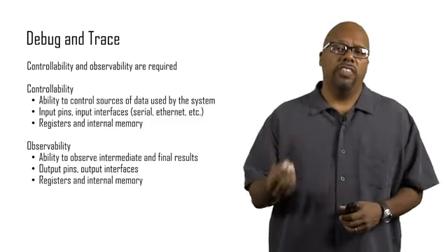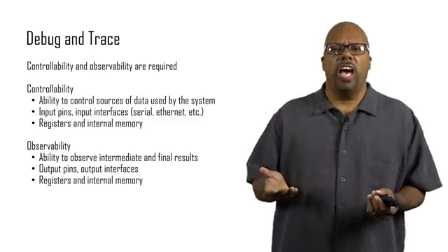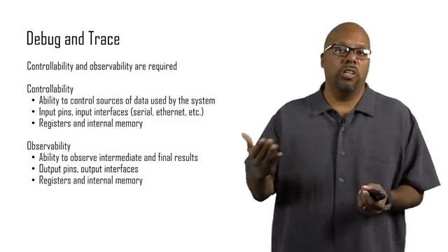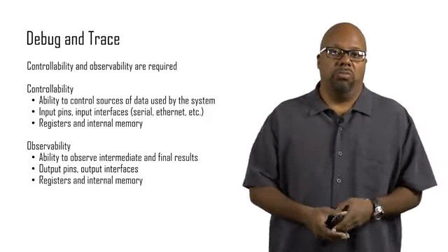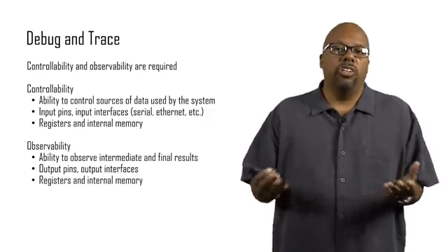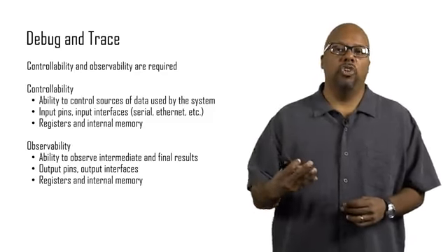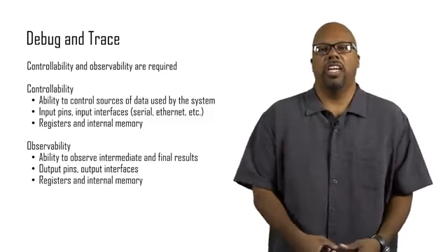So if an output pin changes slowly over time, then a multimeter is fine, right? Multimeters are slow too, so that works. But if the signal is changing fast, say every millisecond, you can't see that on a multimeter. You would need to use an oscilloscope. An oscilloscope basically shows me the voltage over time. So you'd wire it to an oscilloscope, and you can observe the data that way.